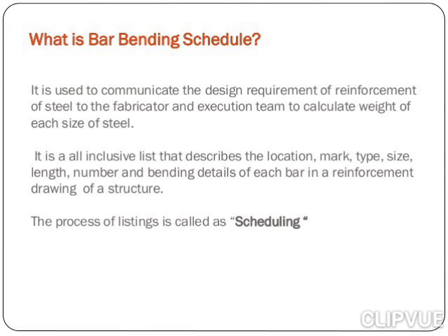Today we are going to study about bar bending schedule. What is bar bending schedule? It is used to communicate the design requirement of reinforcement of steel to the fabricator and execution team to calculate the weight of each size of steel.